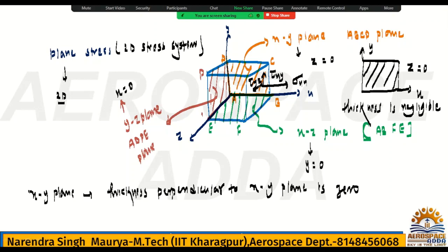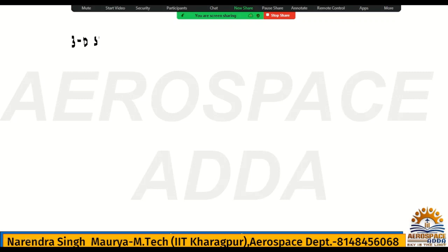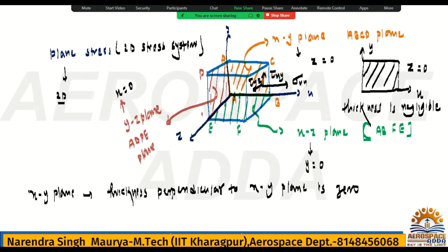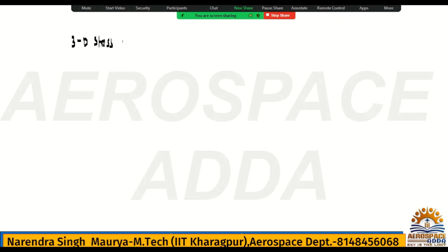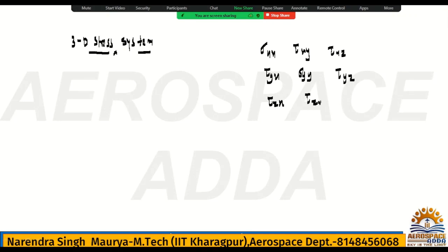So if you check the 3D stress system, we have here sigma xx, tau xy, tau xz, tau yx, sigma yy, tau yz, tau zx, tau zy, and sigma zz. This is the 3D stress system, or you can say stress tensor for the 3D system, right?